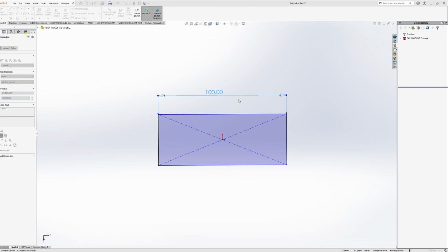However, similar to the global variables tab, if you make an equal sign, it'll give you some other options, just like when it was asking you to assign a variable, or rather a value or an equation. The first thing on the list for your smart dimension now should be global variables. So we can select that and it'll automatically populate the smart dimension with that specific variable.